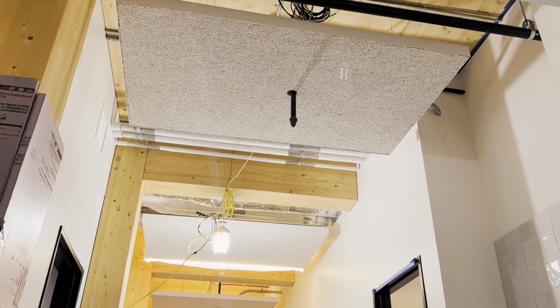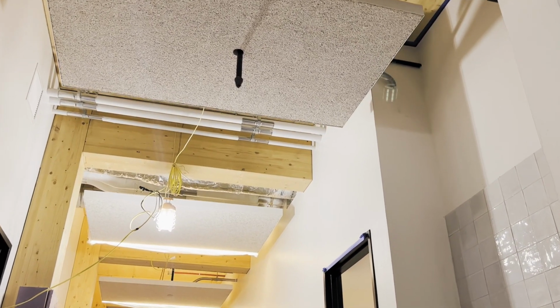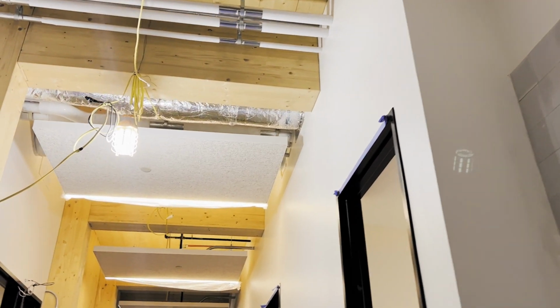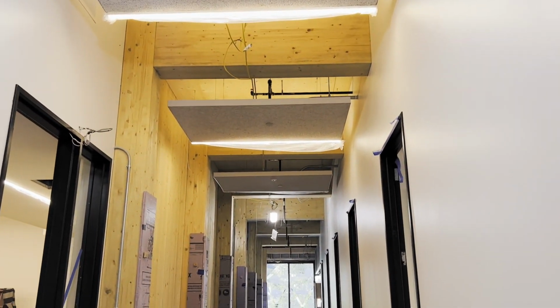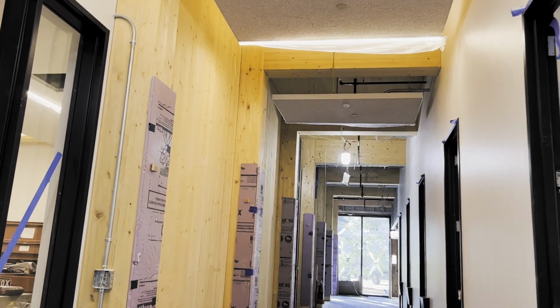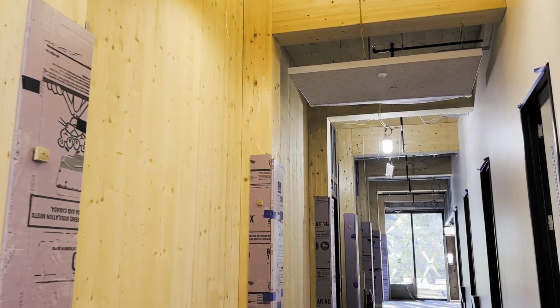The third thing that I would say on this topic is really to do your best in design, integrating the mechanical, electrical, plumbing, and fire protection services in a manner that minimizes penetrations through the timber, and I would say specifically through the timber beams, the glulam beams. By minimizing the number of penetrations, we do two things. First of all, we minimize the structural impact that those penetrations have. Right? A penetration through a beam is going to have an impact on the structural integrity of that beam.